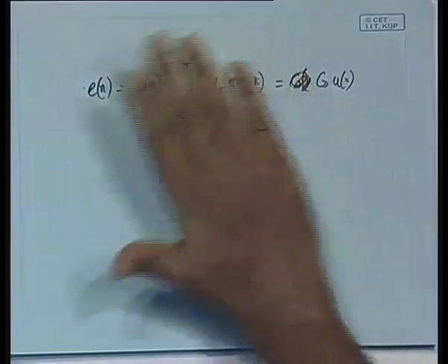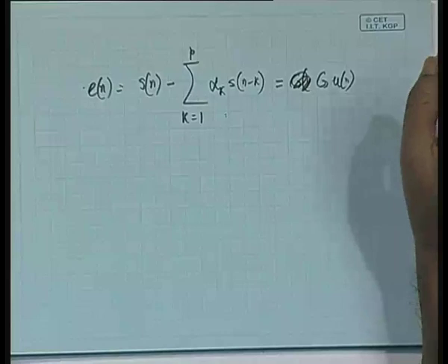The formant resonances would also give some extra peaks, in addition to the genuine pitch period peaks, and we already discussed that it is those extra peaks which often tend to give confusing results whenever you are estimating the pitch period using the autocorrelation on the S of n. So what is the culprit there? The formant frequencies.